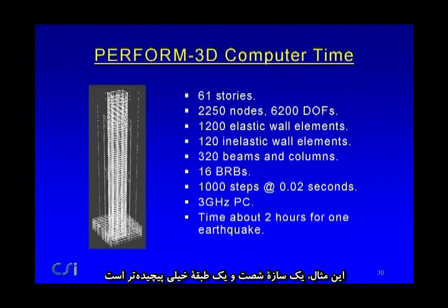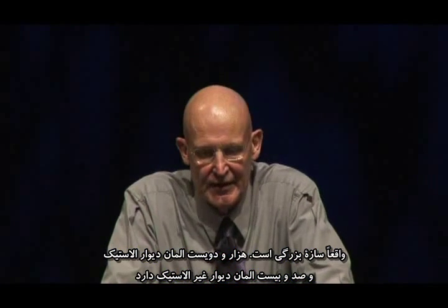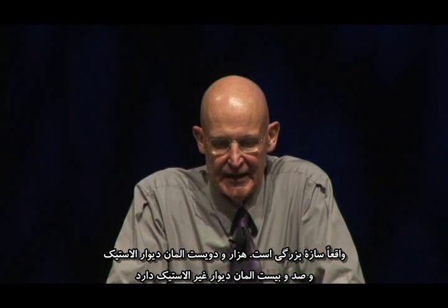This is rather more complicated, 61 stories, a shear wall building, 2250 nodes, 1600 degrees of freedom. This is a small structure by linear analysis standards, but for nonlinear analysis, these are getting to be pretty major structures. 1,200 elastic wall elements and 120 inelastic wall elements.